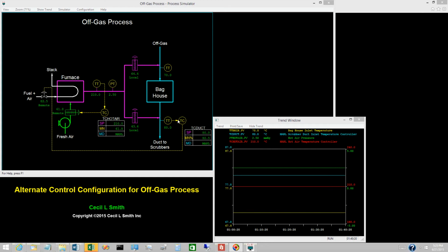What if used alone in the revised configuration? The scrubber duct inlet temperature loop adjusts the heat input. This affects the hot air temperature, but has no effect on hot air flow. As a result, the heat input is being varied by using the hot air in a constant flow variable temperature manner. Since this is very different from what the designers of the process envisioned, tuning the scrubber duct inlet temperature controller will not be undertaken at this time.